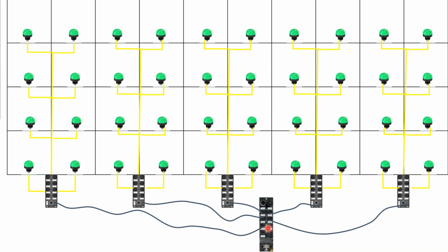So this worked out to be a very, very cost-effective way of doing this. Simple. We didn't have to run multiple Ethernet cables, and we were able to use just the 3-wire unshielded cables, which made them very easy to route. And also, even though I'm using different colors for the IO-Link cable and the field cables, they actually could be the same. So pretty slick system there. Again, this wasn't an IO-Link request. It just made sense to take advantage of what IO-Link has to offer.